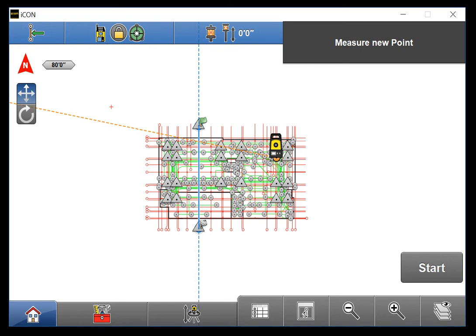To understand these objects, we must first define our understanding of a line. Note, if you try selecting a line from the background and nothing happens, it's because you don't have your DXF loaded as reference data. Please see Video 11, Import tab, or Video 7, Project Setup and Organization for instructions.